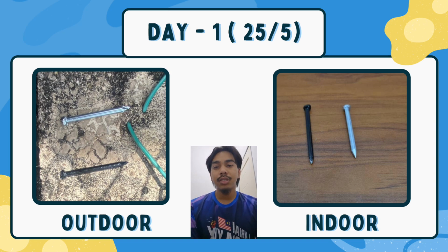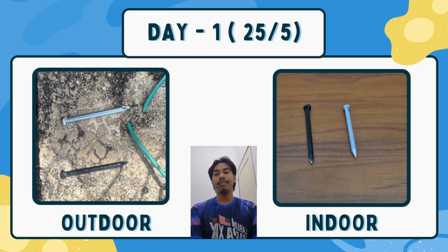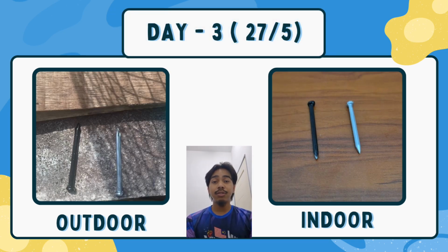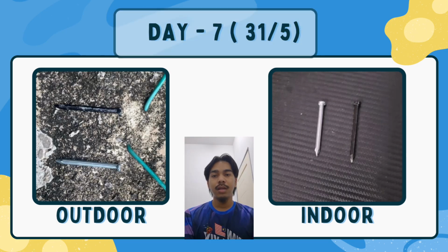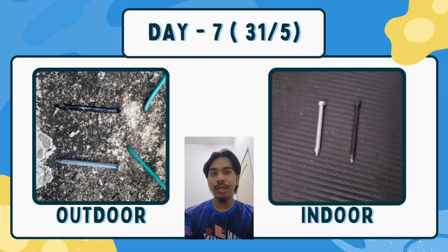Meanwhile, for indoors, uncoated samples show no signs of corrosion at all. On day 9, for the outdoor nails, the nail coated with the spray exhibits areas where the protective layer had partially worn off, exposing sections of the original nail surface. Despite the degradation, no visible sign of corrosion, such as reddish brown rust, was observed. The indoor nails also remain free of any corrosion and had a slightly thinner spray coating that continued to cover the surface adequately.